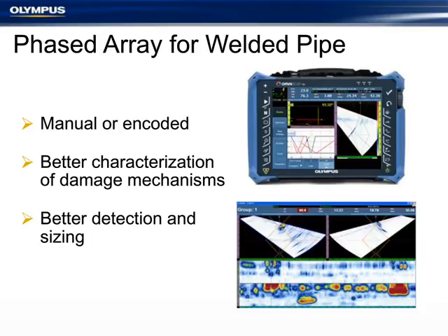We can actually put a weld overlay so that we can see the profile of the weld to help us characterize and position defects, as well as make the reporting clear for all the people that need to understand what's going on within the weld. Also a possibility of doing ray tracing, where the defect is actually physically located as we position the flaw, either on the bevel line or in the root or into the base metal. So it helps add a lot of tools for the operator to help characterize and correctly identify the defect and the extent of the defect.